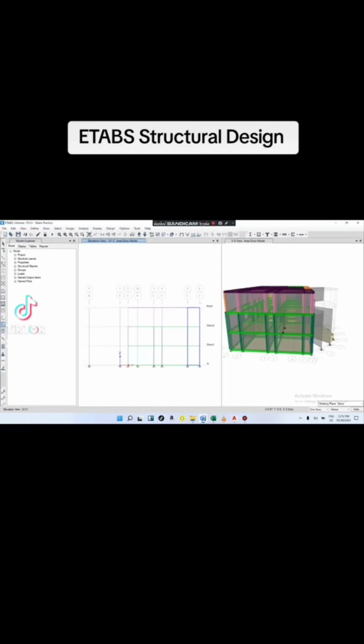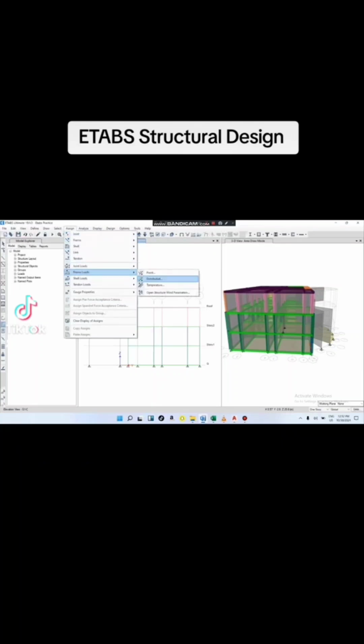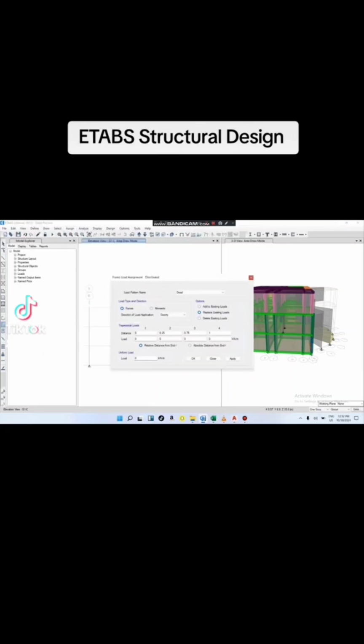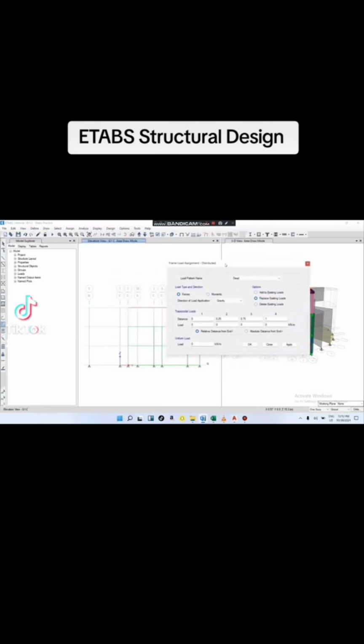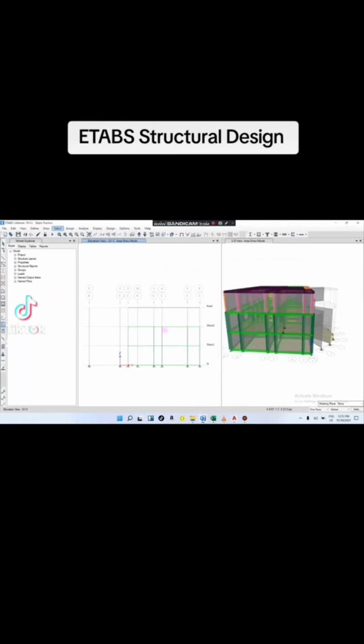Now we will go to the beam. So we already entered the slab load. We go to the beam, changing the elevation to C. And then we say assign frame section, uniform load. First again we have to select the section that will receive the load.